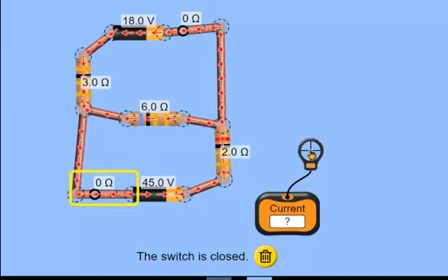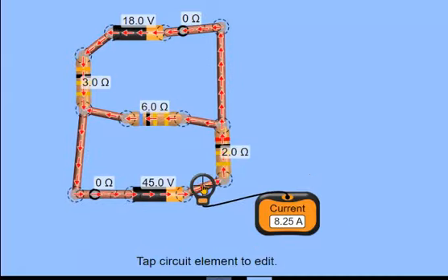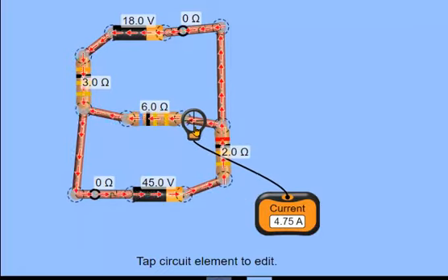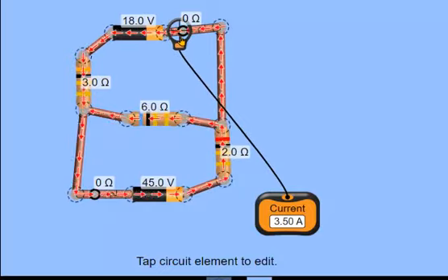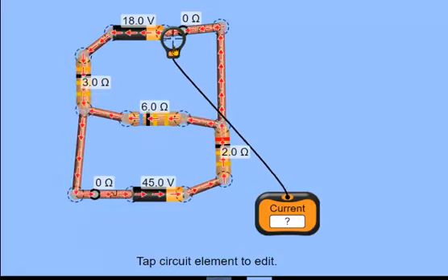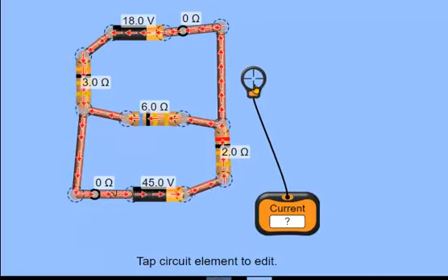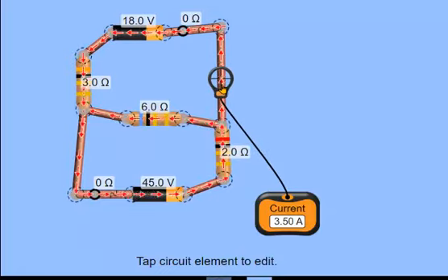Okay, let's see what the currents are. I gave it the correct numbers here. Here's the I3. Indeed, it is 8.25 amps. Here it is indeed 4.75 amps, and here it is indeed 3.50 amps. This particular ammeter does not discriminate in which direction the current is going. This is also a no contact ammeter where you simply clamp it around the wire and you don't have to interrupt the circuit here. It works with the magnetic field that is being produced by any kind of current and the Hall effect.